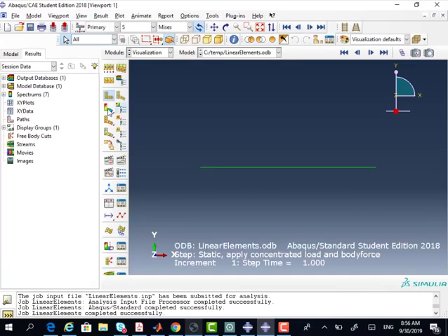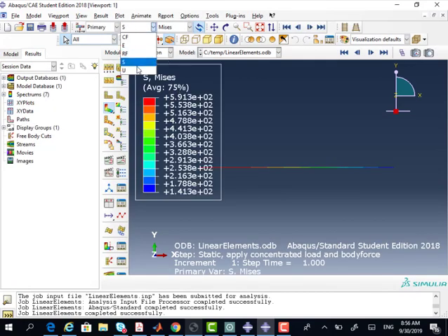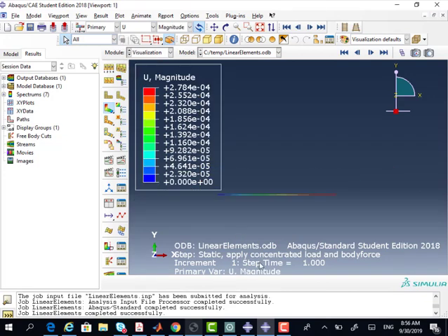And then I visualize the results. So let's start by selecting the displacement. And let me actually move a little bit so you can visualize what's happening. So you can see here that the displacement changes along x, even within an element. So this is the first element, and you see how within that first element, there's some variation in displacement. Within the second element, within this third element, and within this fourth element. Obviously, the magnitude increases as you move away from the fixed node.